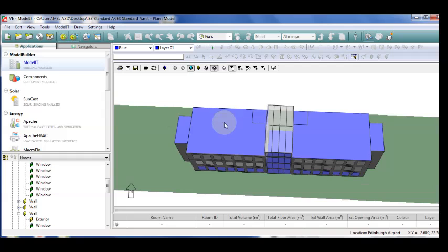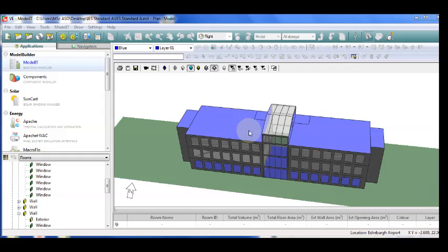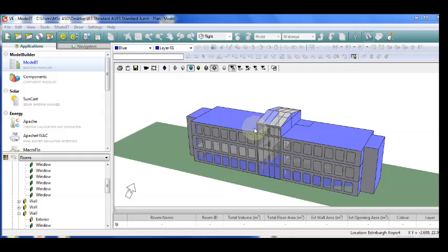And you can scroll around this particular slightly more rendered model using the similar sort of mouse tools that you've got for SketchUp, that is left clicking and dragging, and you alter the angle there, and you can see it's rendered with different kinds of shadows and so on. And up here you've got some tools which give you viewpoints that you can set, and you can actually start to see inside the building in certain things.